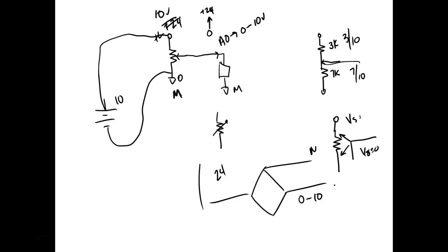And then you have to figure out, is it 120 volts or 240? We have a lot of AC PLCs out there that run on 240. So there's a lot of industry that don't have 120 volts available out there in the control. And why? Because what advantage does high voltage have over low voltage? Less current to produce the power, right? You understand? Which means I can use what? I can use smaller gauge wire inside my system, which means it's going to be a lot cheaper to install. It's not more efficient. It's just cheaper to install and cheaper to run, right?